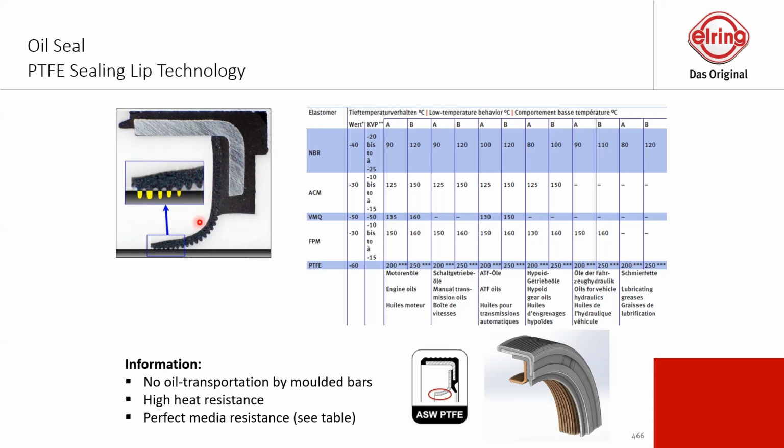The other thing we're also missing is a spring, because we no longer have a spring that puts pressure against our sealing spot. Nowadays we have only a drag lip, which lies on the shaft and is no longer pressing against the shaft. This lying is reducing friction a little bit, and the addition of the PTFE material is also reducing the friction. That's the main thing.